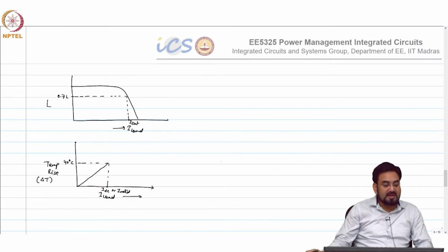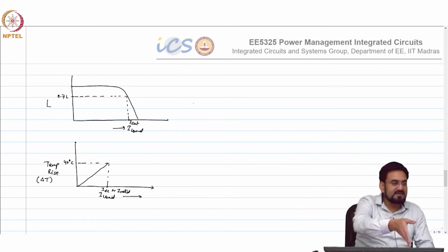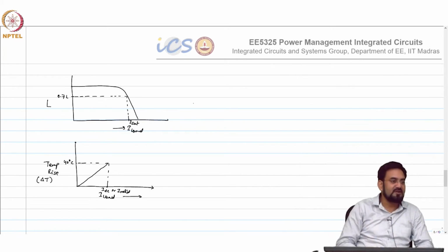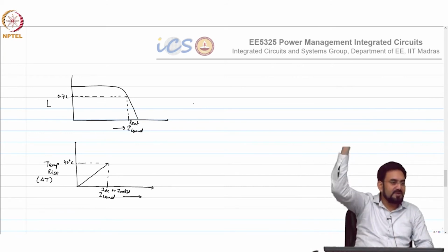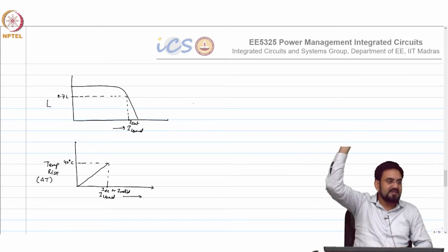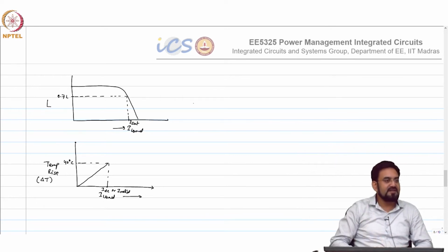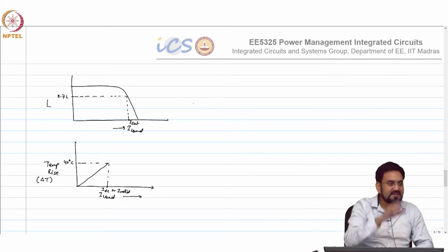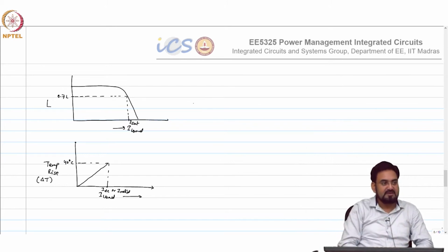So for those kinds of inductors, you have to be a bit careful. You have to have enough margin, because the moment it hits saturation, your inductance will drop quickly and increase your peak current. Let us say 1 microhenry drops to 100 nano, a 10 times increase in the peak current; it will break everything, the FET. That is one of the reasons you require a current limit, so that you can turn off your FET immediately and protect the inductor as well as the power FET.